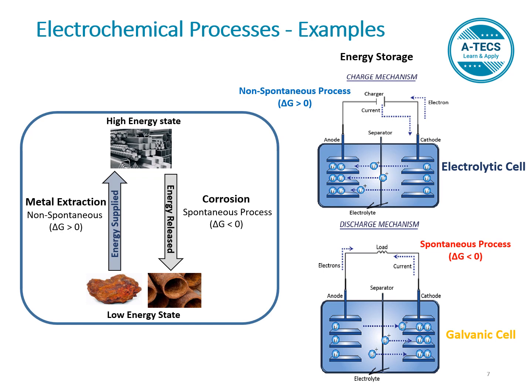Corrosion products are formed because those are at their lowest energy state. So all the metallic species tend to achieve their lowest energy state, and during achieving that lowest energy state, they release energy. That is why this process is always spontaneous in nature, and corrosion is a clear example of a spontaneous process.